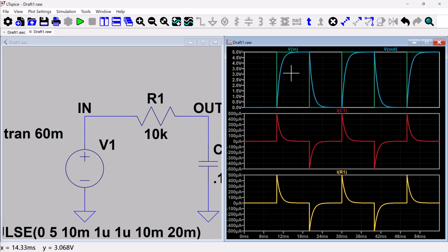And then a quick measurement, like if you wanted to do a really quick measurement on something, you can actually use that zoom feature to do that. So let's say I wanted to measure, I don't know, the period of my waveform just to double check and make sure I set that up right. You can use your zoom feature, but don't let it go. If you look at the lower left, you'll see what the X distance and the Y distance is from the corners of your zoom. And so you can use that to make a measurement really quickly. There are other ways to make measurements, but this is the quickest way to do it, and easy for me to show you since I'm already showing you zoom.